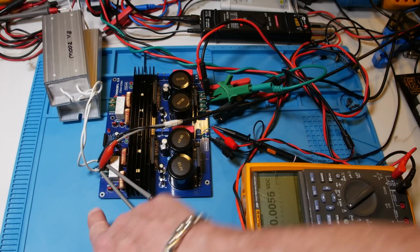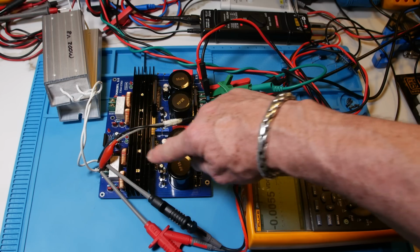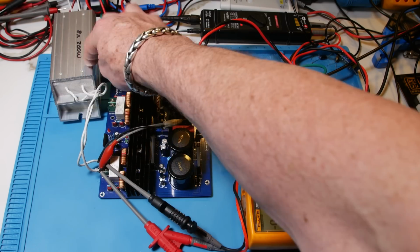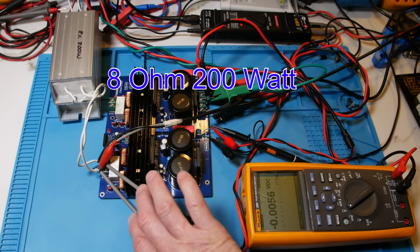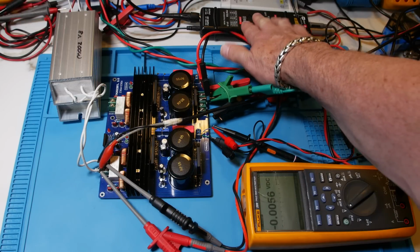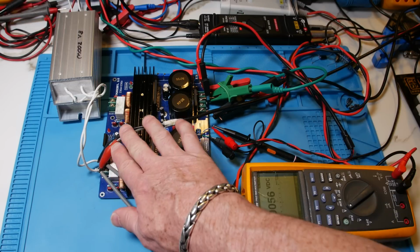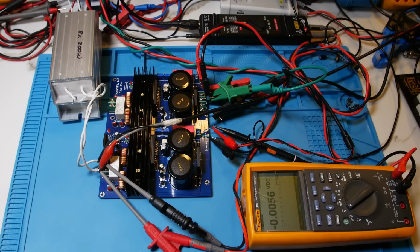LC filter. There's little C's down here in the L's and C's over on this side. And then we come out into this 8 ohm load resistor that's sitting on top of a 4 ohm just for heat sinking. Then we have the differential probes here that come over to the Instek, set in the ×20 position. And this lead set here goes to the THD meter.